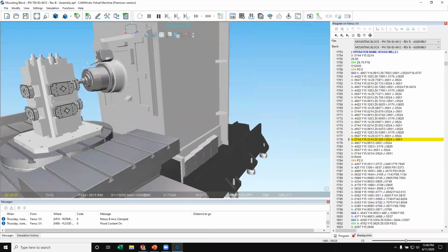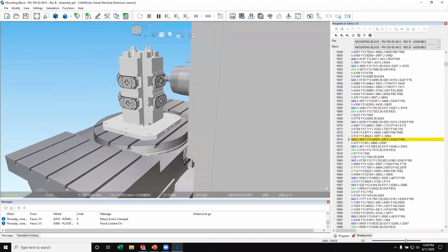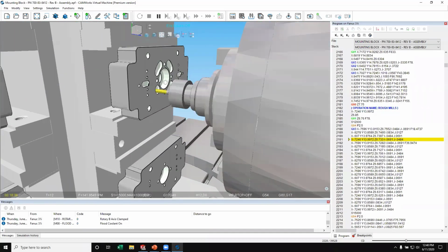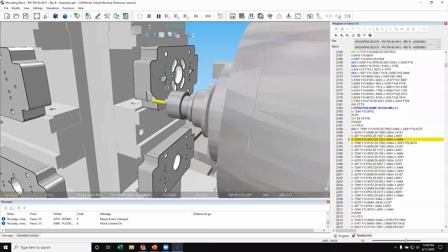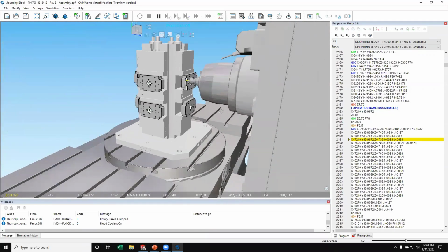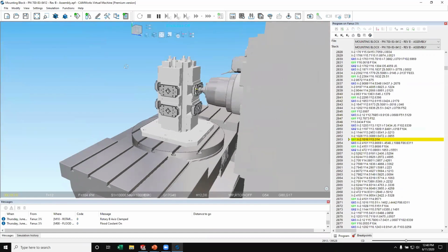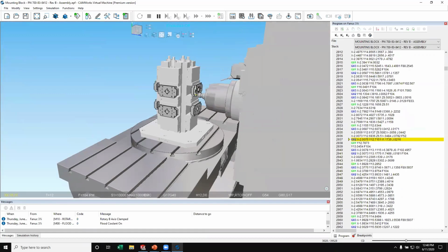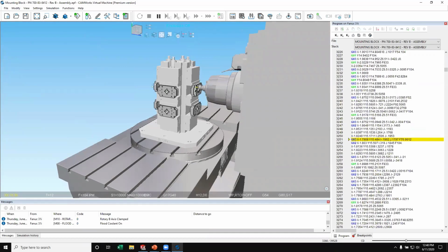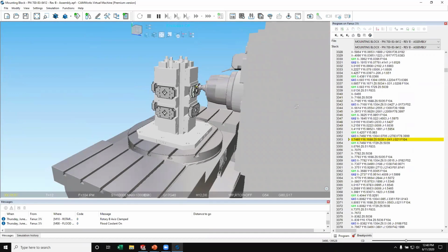And yeah, you can move this around too, and I can get different views and whatnot. And this will alert me if I have any collisions or anything like that. I can zoom in, you can see it milling those pockets out with a volume mill and starting to hit those, etc. That's kind of how that works, guys, and you can see we're simulating the code with the 4-axis code. So I hope that shows in the 4-axis how the automatic feature recognition and rules-based machining can be used to speed up programming even in complex detailed parts with multiple parts in the 4-axis realm.